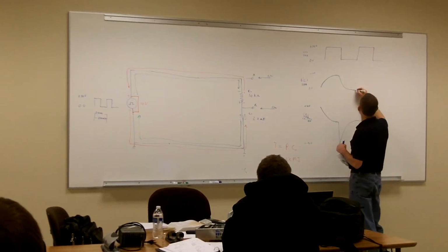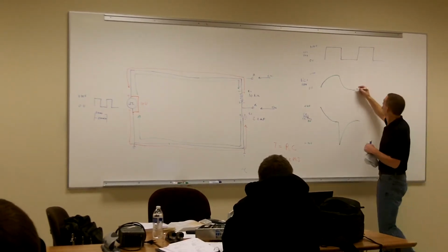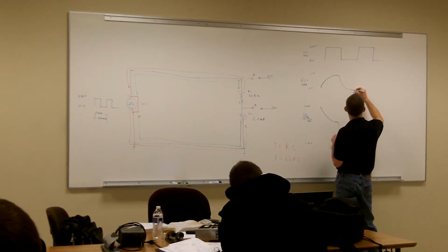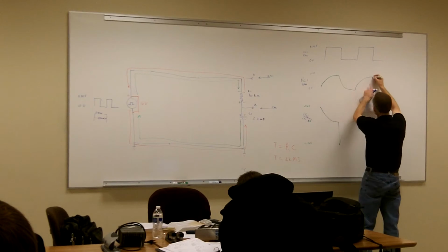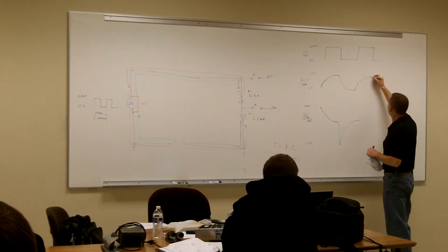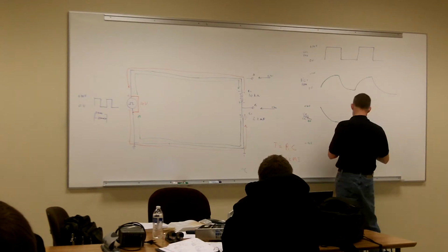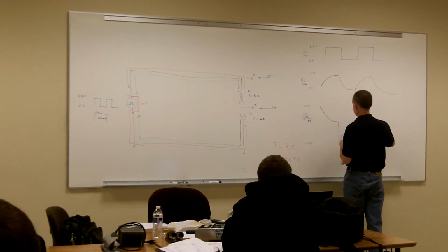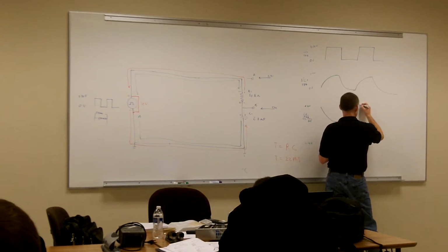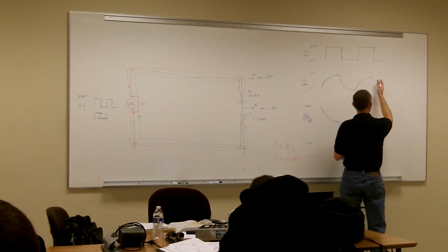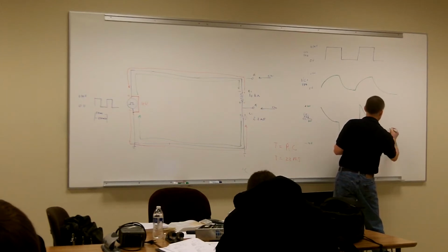Then if we went ahead and drew in our other 2 waveforms, because when we're graphing out waveforms, we always like to graph out 2 complete cycles so somebody can see where the cycle starts to repeat. So then I transition to a high, the capacitor is going to charge up, then it's going to transition from a high to a low, and then my capacitor is going to discharge. And then what's going to happen on this one is the same thing. Once that capacitor acts like a short, my voltage across my resistor is going to go up to 10 volts. As my capacitor starts taking all the voltage, it's going to drop down to 0. Then that capacitor is going to act like the source. And then my resistor is going to drop down to a negative 10 volts and then back up.